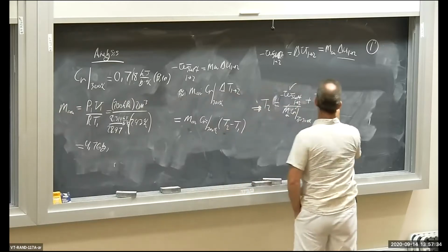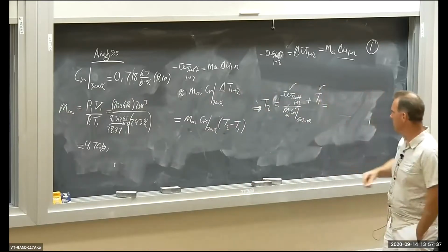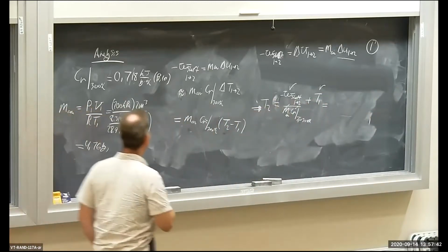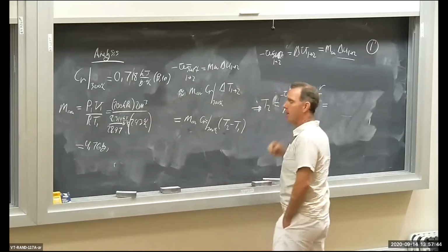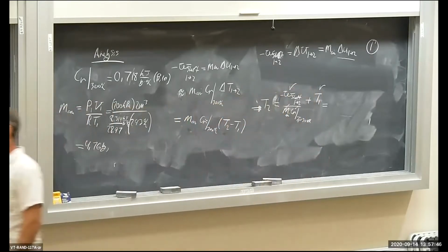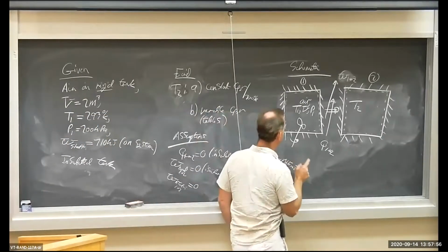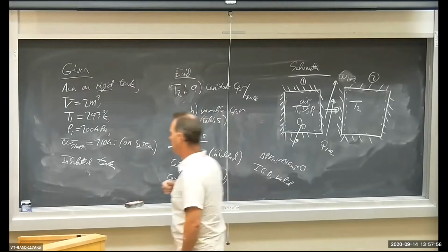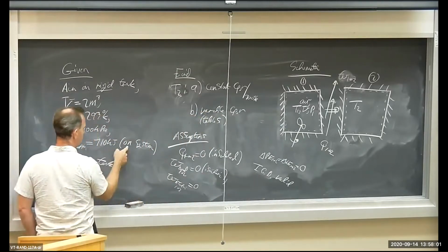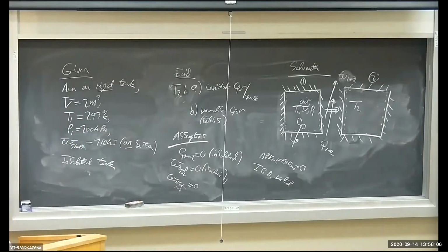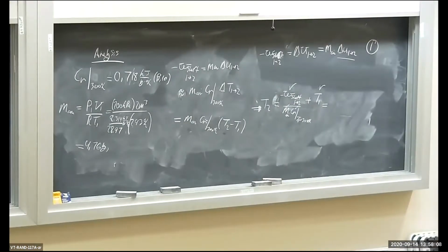Let's plug in. W shaft. Remember the energy balance. In the energy balance, W is by the system. If the system does work, work is positive in the energy balance. We're told that the shaft is doing work on the system, 710 kilojoules on the system. So the numerical value that we're going to plug into the energy balance is going to be negative.